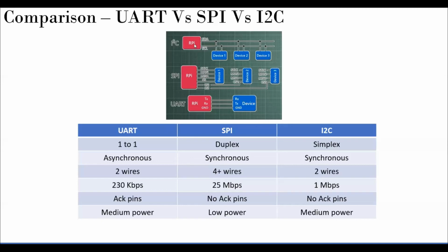And then I2C is a 2-wire system, 1 for data, 1 for clock. You can have 2 raised to 7 or 2 raised to 10 devices connected to it. SPI can also have 2 raised to 7, but then you need 2 raised to 7 chip select lines, which is definitely not feasible.